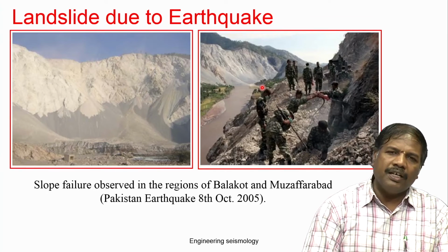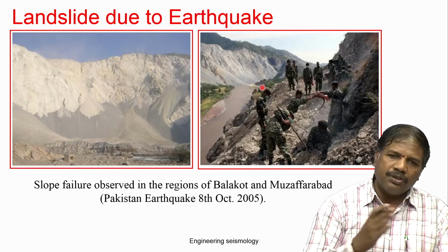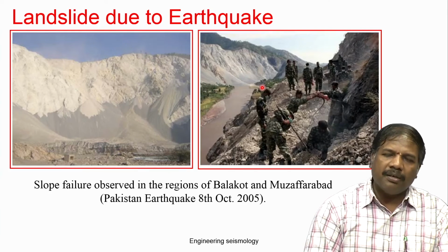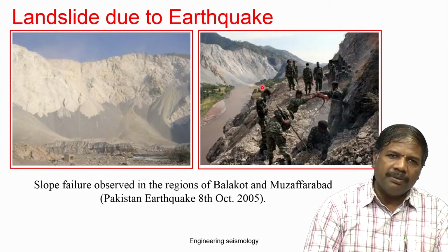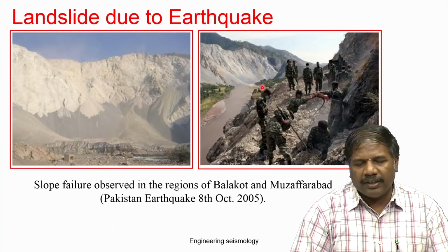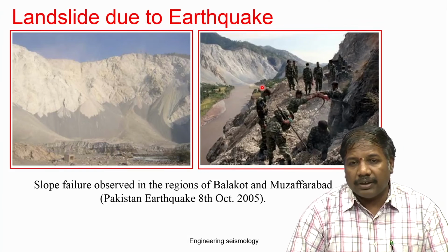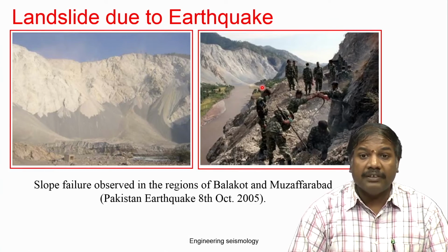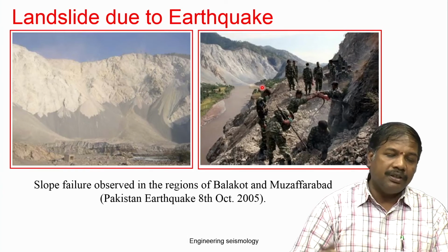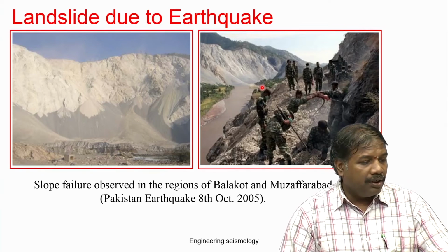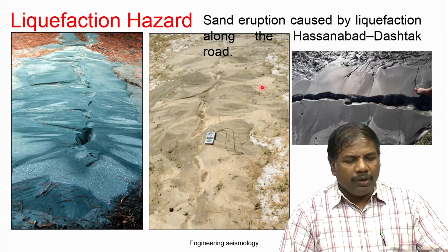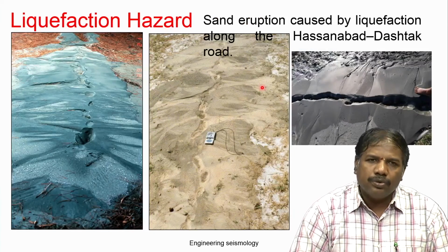The earthquake creates an additional force in the slopes, which become unstable and collapse, causing a lot of disturbance, and that disturbance is basically the landslide. So, even a small magnitude, okay, 5.5 or 6, a moderate magnitude, can cause 1500, 2500 landslides. This was some of the history that we can take from past earthquakes. So, this will be another major hazard due to the earthquake. So, we also try to understand liquefaction.